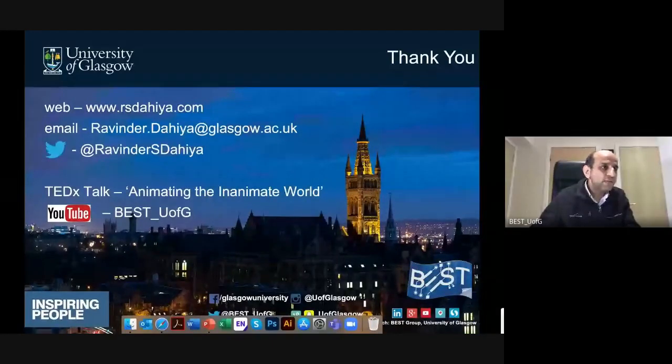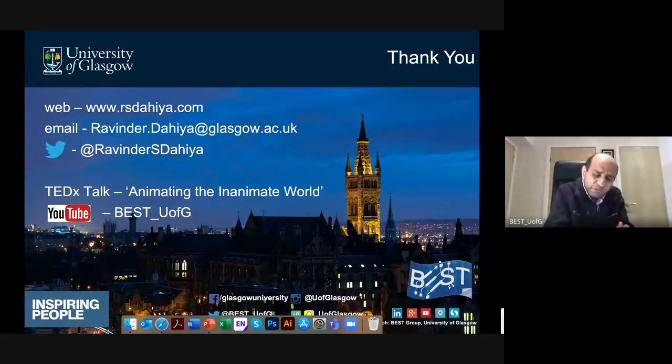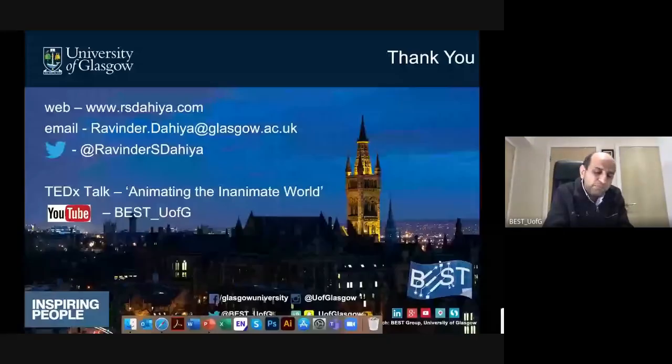Well, okay, I'll continue. So as I mentioned, there are several materials that are being used for the piezoresistive layer. And one example I mentioned, zinc oxide nanowires itself, which we print, could be a possibility. Another example you can pick up is silicon nanowire, where when you bend, the resistive property changes, and then they also could be used as sensors on polyimide film to achieve the various sensing properties.